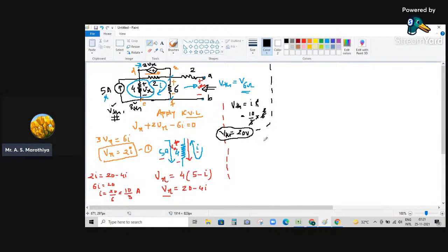When we have independent current source, we are going to deactivate them by open circuit. So these points we have already discussed. Why to deactivate voltage source we need to short them, why to deactivate current source we need to open circuit them. These points we have discussed in the previous section.